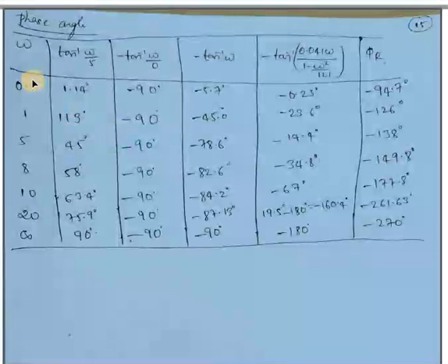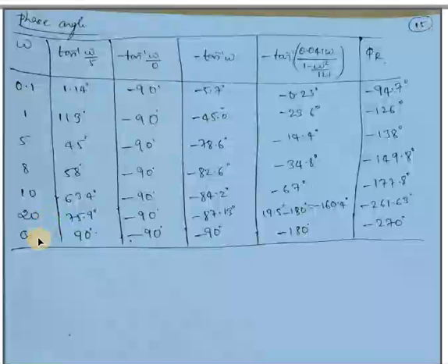After that, you need to construct the phase angle table. For that, we have a zero there, so tan inverse of omega by 5, and the remaining poles with negative sign. Vary omega from 0.1 to 20 and at last infinity. You can take values randomly, but try to include the break frequencies. Then you calculate the respective resultant phase angles.